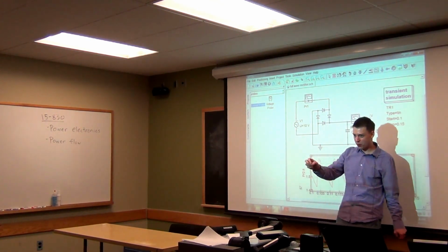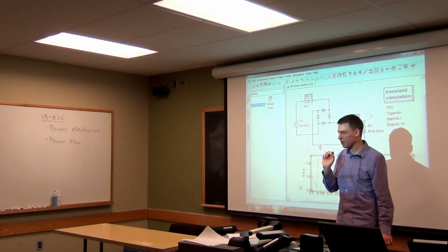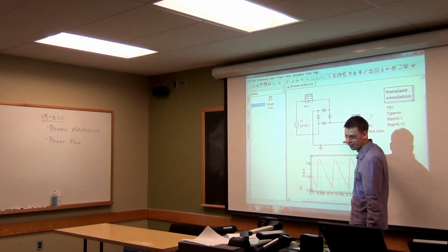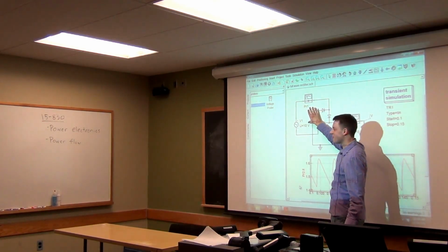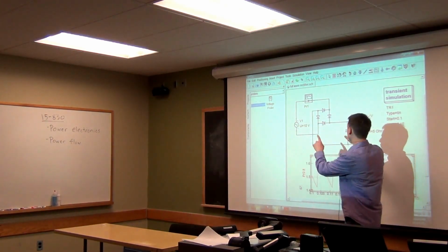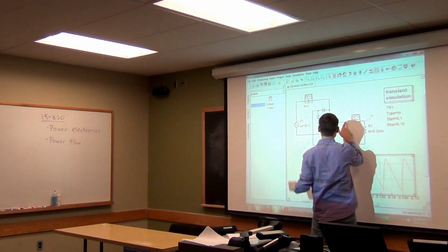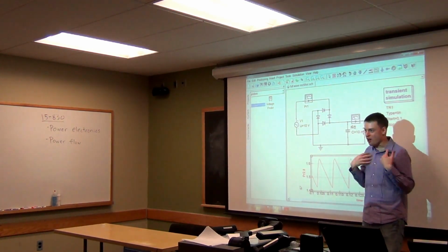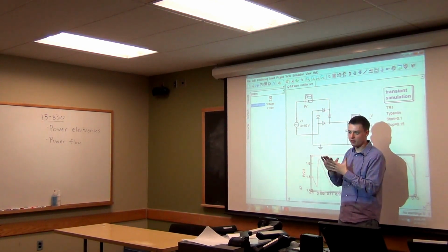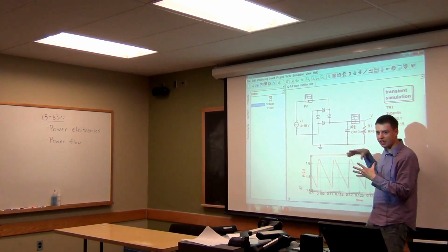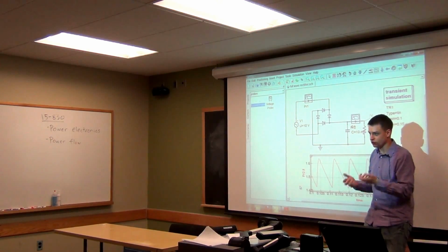There will be times there where it's drawing no current, and what's happening there is the capacitor here is providing the current, and it's providing the voltage. And then there are times when this voltage swaps here, so this one becomes higher than that there, and then it draws all that inductive current. So absolutely, and that's very important actually, that the device is seeing a DC signal, a DC voltage source effectively.